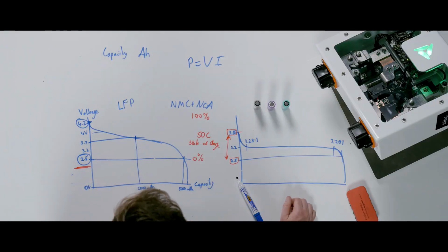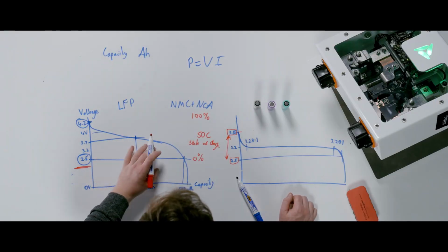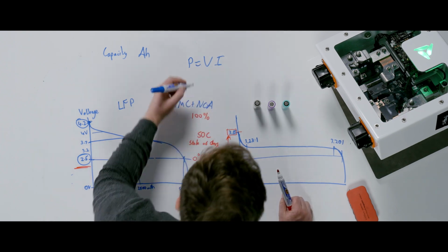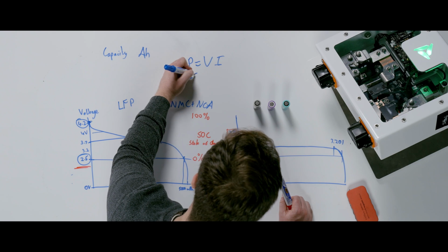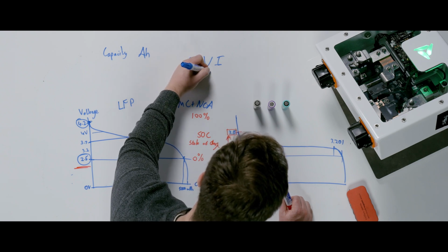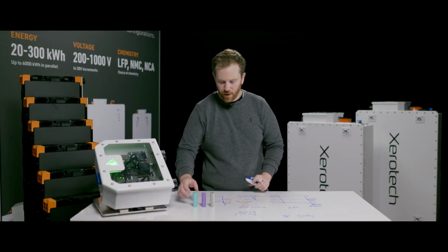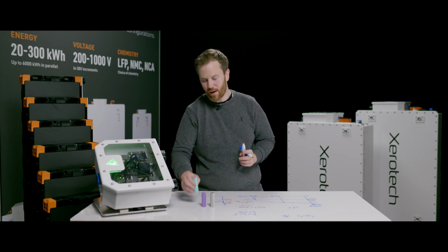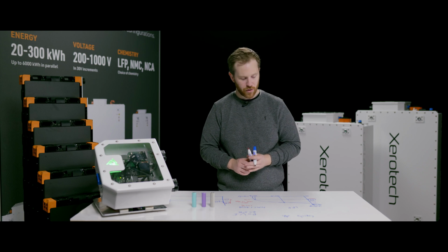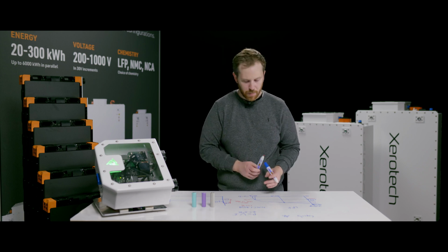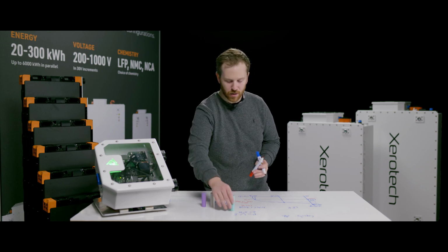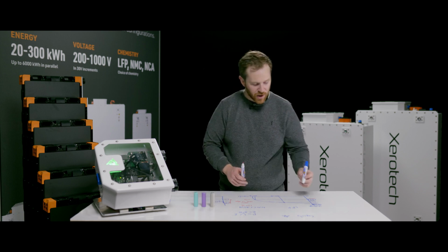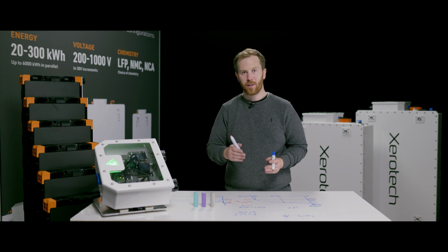The next thing we might talk about with the battery cell is that, as we talked about our resistances here, you might recall that the energy lost in a battery is I squared R. A battery is not a perfect store of energy. A battery basically has a tiny resistance inside of it that limits the amount of current that can flow. And what that means is when you put a battery in a circuit and let the voltage drive a current around it, you'll actually see the voltage on the terminals drop.